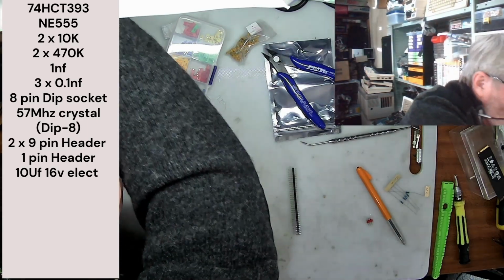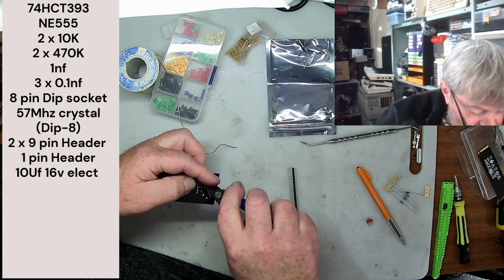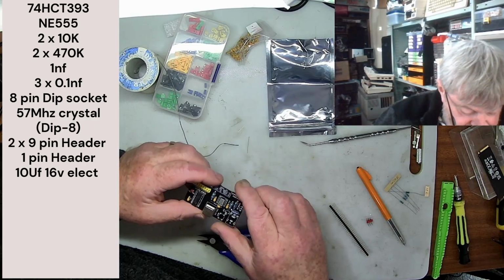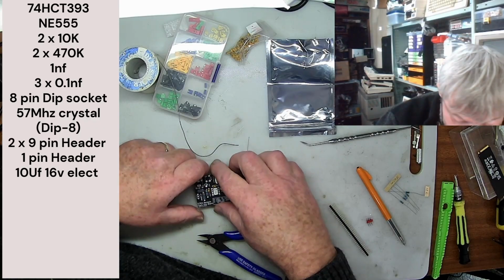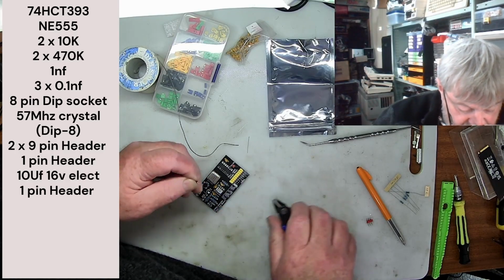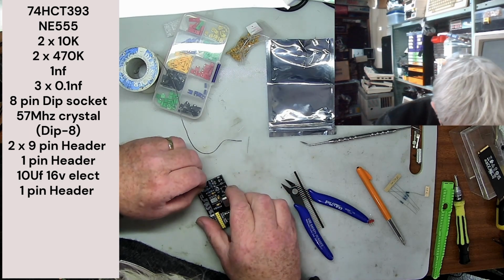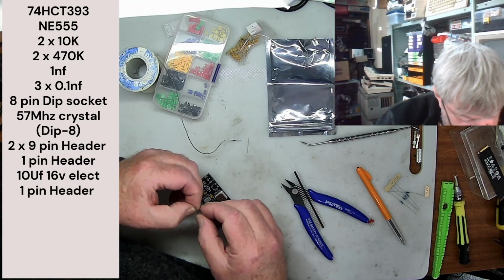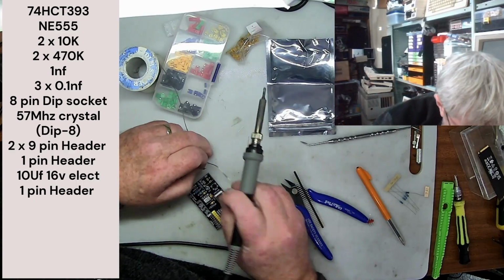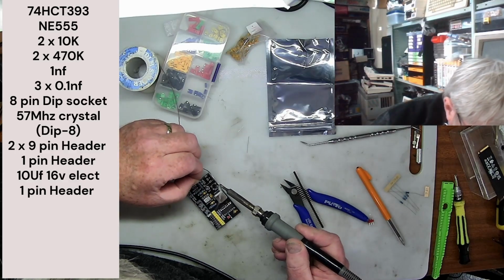That's cool. That's done. Clip the legs on that one. And when I've finished all this, I'm going to give it a good clean up with isopropyl as well. So those are there and there. So I might tag a pin onto that resistor on the back of this resistor here for a reset pin. Let's put a bit of solder on this first. A bit of solder on the iron.